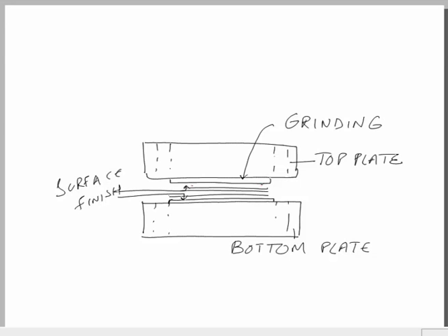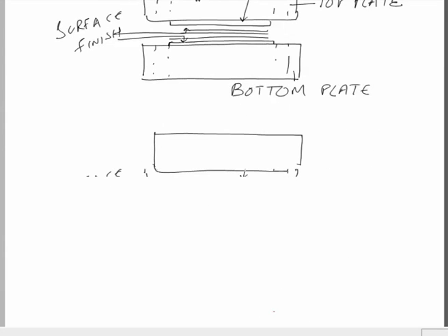Alternate layers of the fibrous reinforcement and the polymer would be put on this particular plate. So, this plate would not be in use initially; we will only work on the bottom plate, and then once the layup is ready we will bring the top plate and place it on top of the bottom plate in order to get a composite. So, this would be the construction or the structure of the composite that we will be getting here. The structure of the composite would be a layered structure.